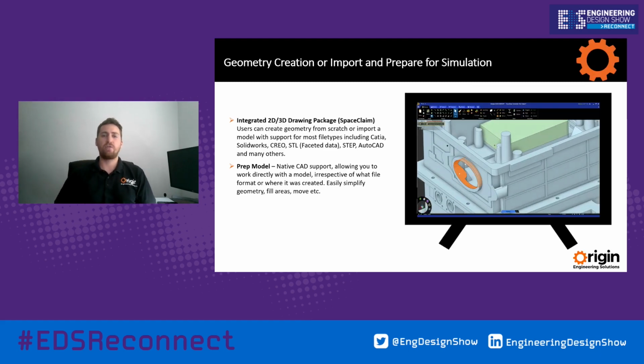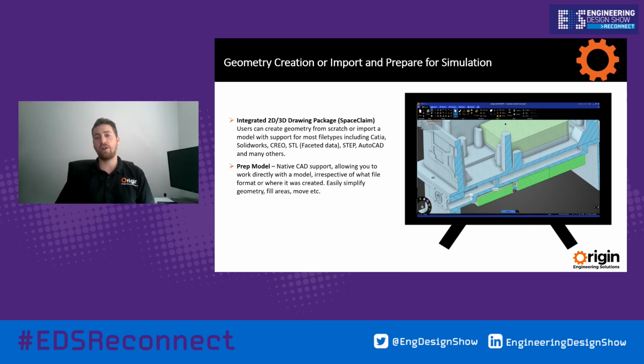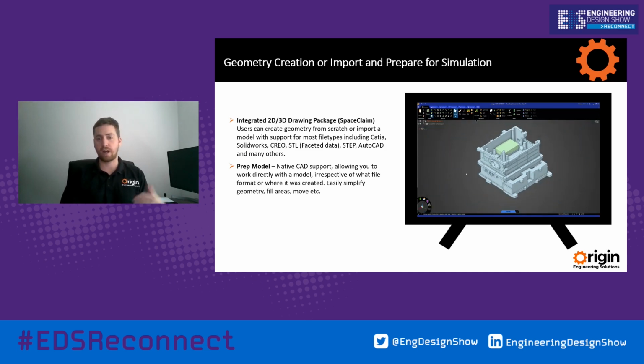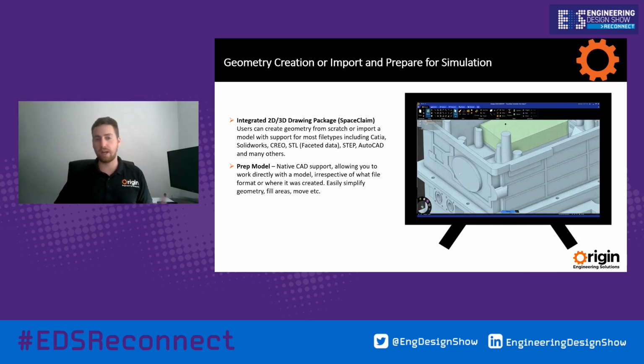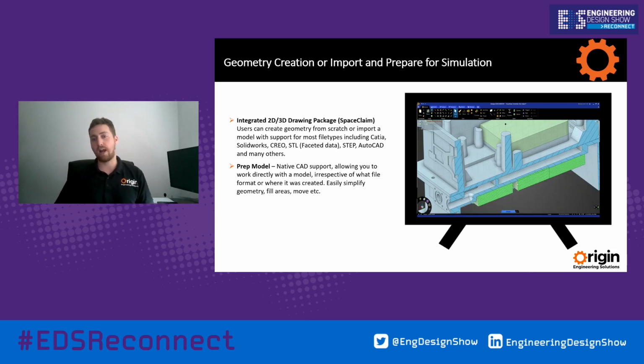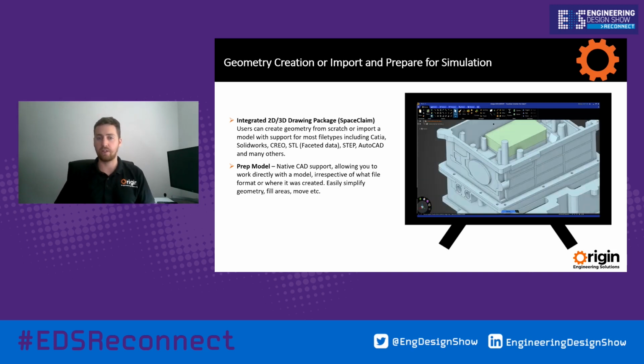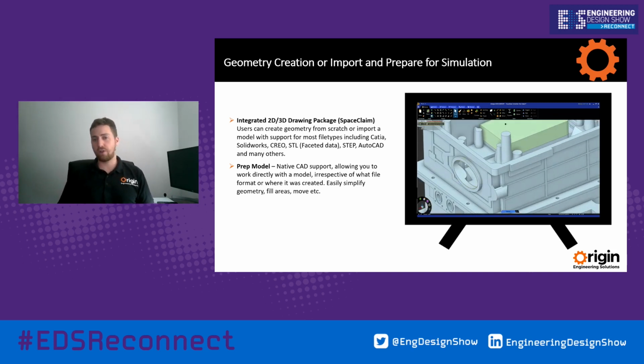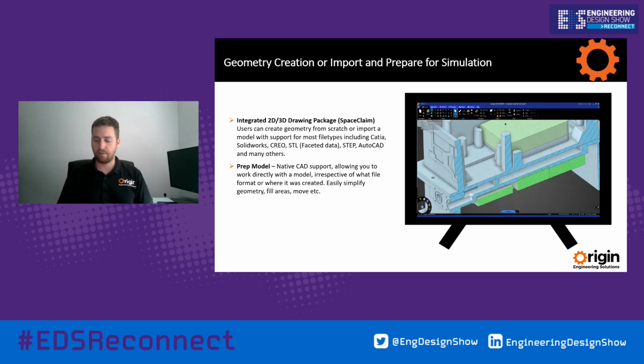The Ansys Discovery workflow is generally that you can design within Ansys Discovery, or you can import a model. We can import models from anywhere, so it doesn't matter where your model was created, whether in SolidWorks or CATIA. We can import it into Ansys Discovery, modify and work on it as if you created it within the product itself, and very quickly set up simulations on it. So that's the first step: import your model and prep it for simulation.